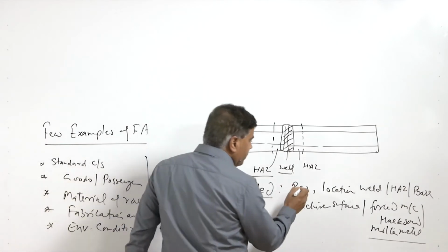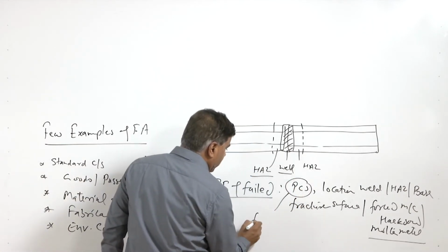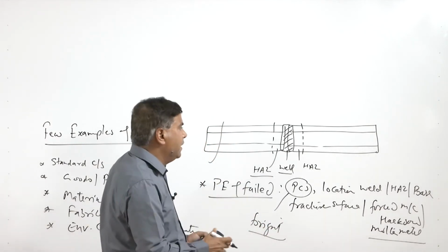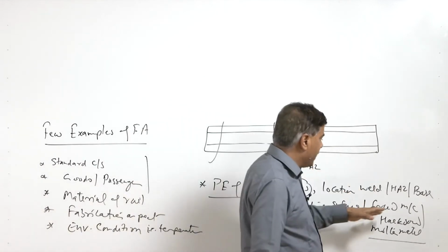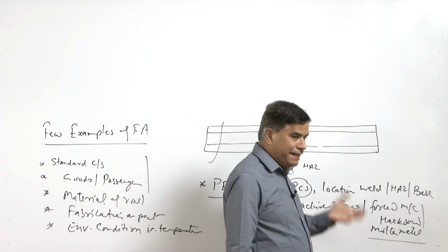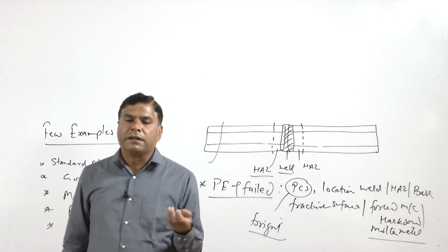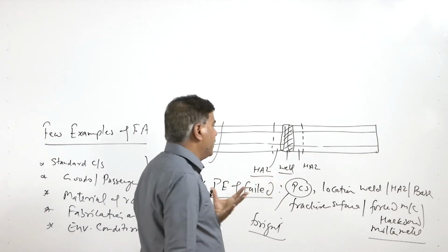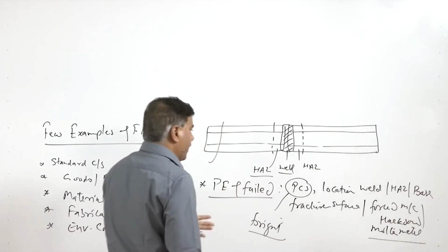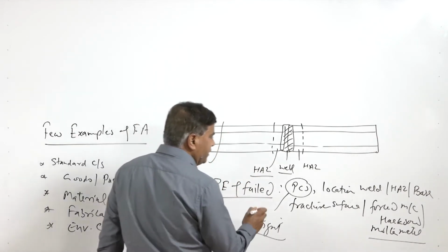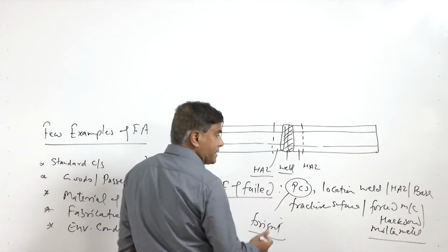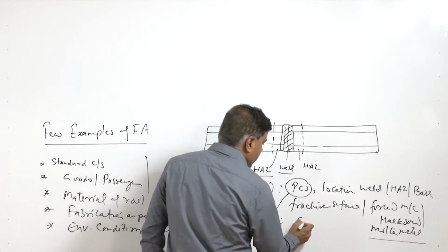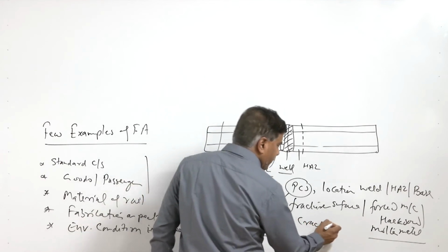If the fracture pieces are bright, that reflects that the fracture surface is freshly created, and if it was cut it will have its own marks on the fracture surface, and if it is melted forcefully then it will have the molten metal or cast layer over the fracture surface. So each will have its own morphology and visual appearance. That can be easily identified, the way by which the separation has taken place, whether there was any tampering or it has happened due to crack propagation.